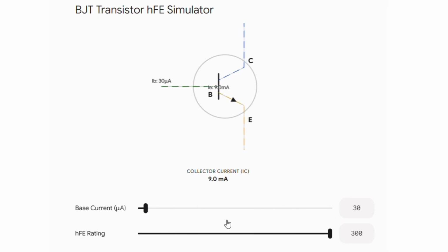So 0, very little amplification. Low hFE occurs beyond the transition frequency. When you go for higher frequencies like radio frequency, there is something known as transition frequency. At transition frequency, hFE will be 1. So minimal gain will be there, and actually no gain, because when hFE is 1, there won't be any gain. Here the minimum hFE shown is 10.